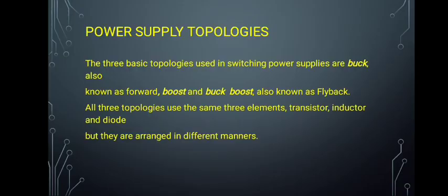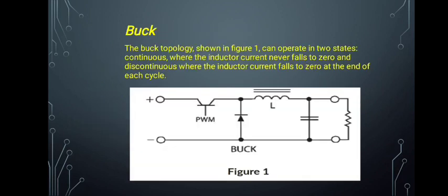Power supply topologies. The three basic topologies used in switching power supplies are buck, also known as forward, boost, and buck-boost, also known as flyback. All three topologies use the same three elements: transistor, inductor, and diode, but they are arranged in different manners.